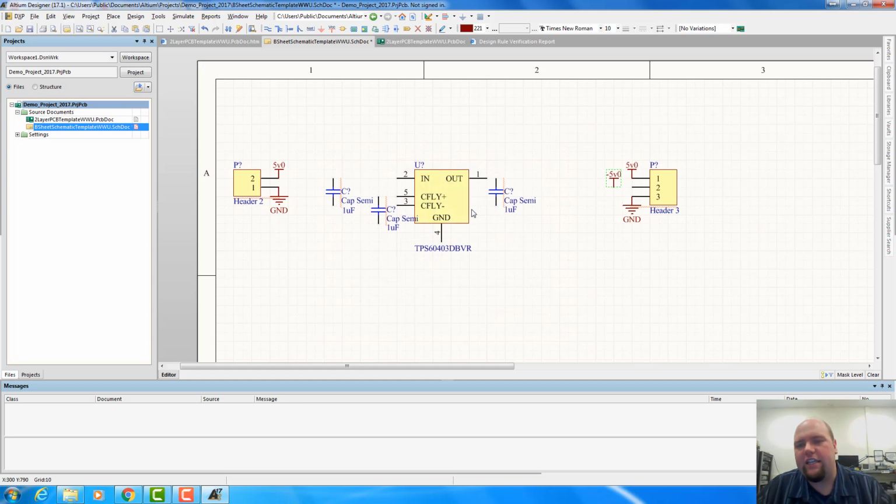This is actually not ideal. We wouldn't normally want to write a negative 5V0. We'd want to find a better naming convention like neg rail, pos rail, something like that. The negative sign is very easy to miss when you're just quickly scanning this document, so it's not the best idea, but it's good enough for now. Okay, so we have these rails here.